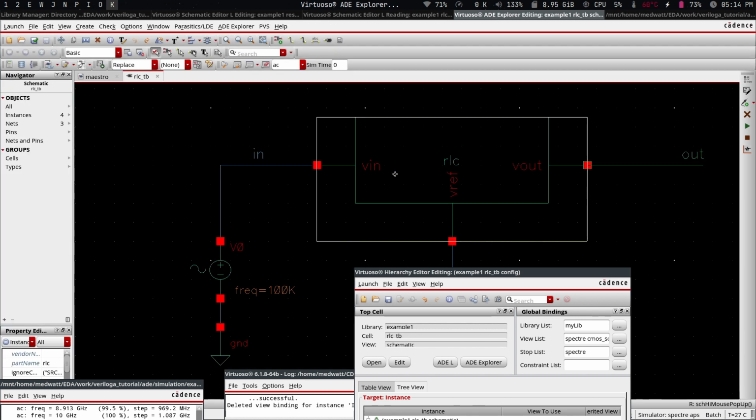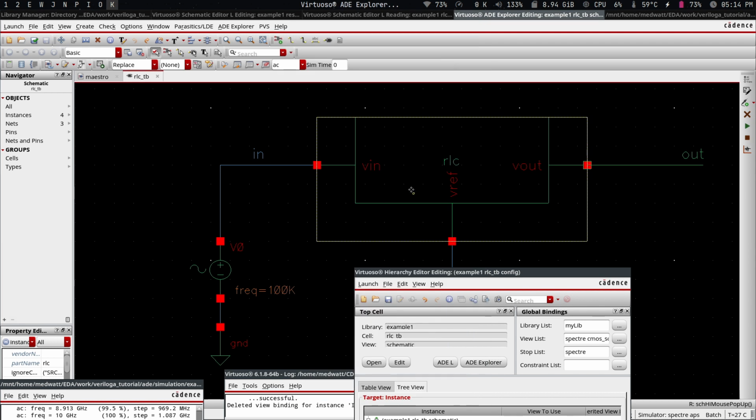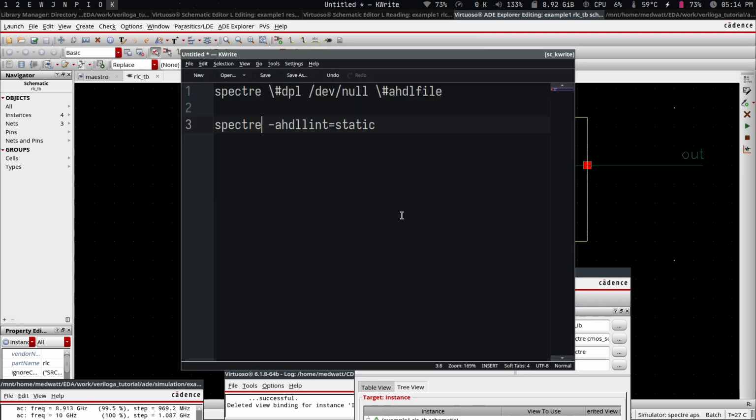So what you need to do is, you have to specifically, explicitly tell the simulator to pass these values from the top view down into the bottom views. How do you do that? You do that with something called p-par, and then you specify the name of the variable that you want to pass down. So let me just show you for now.